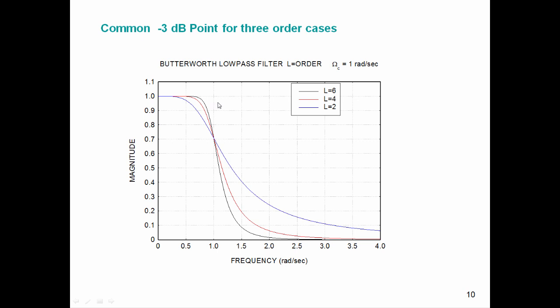But the trade-off, and I have not demonstrated this to you, but just for now, take my word for it. The higher we increase the order and the closer we meet the ideal filter, the more likely we are to have numerical instability. And you'll find that when we actually get around to filtering a signal using the MATLAB vibration data GUI package, one of the outputs that will appear in the command window is an assessment of the filter stability.